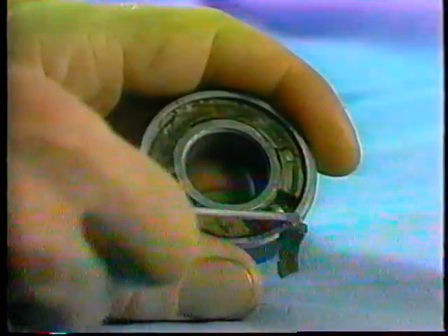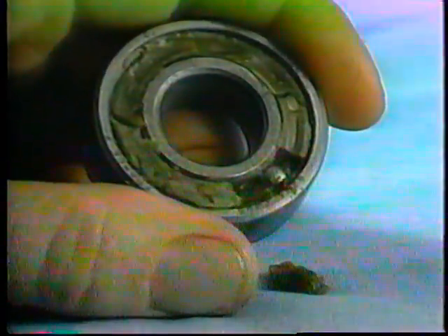Grease may also become stiffer if too much oil bleeds out of the grease. Some bleeding is normal because that's how the grease provides its lubrication film. But if too much oil bleeds out, the remaining grease will be dry and hard, unable to provide the required lubrication. It will have to be removed and replaced.